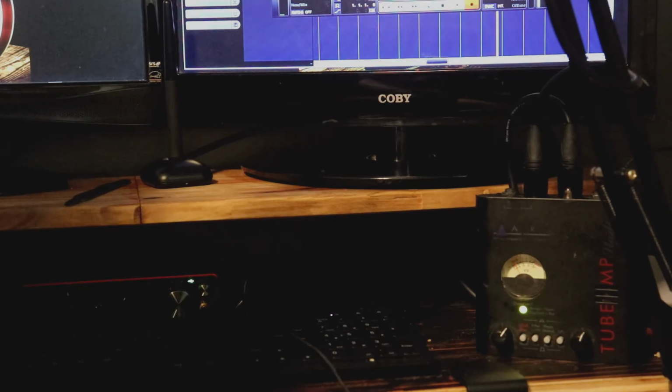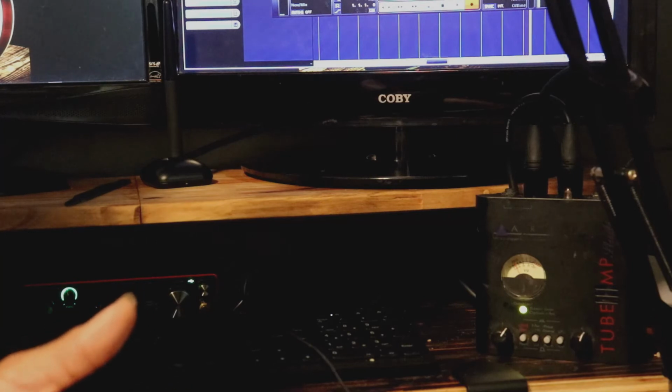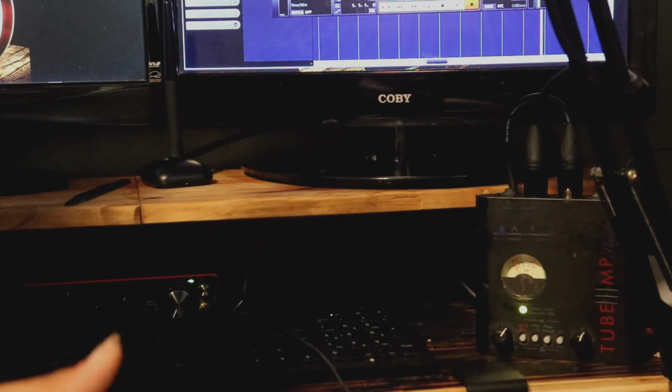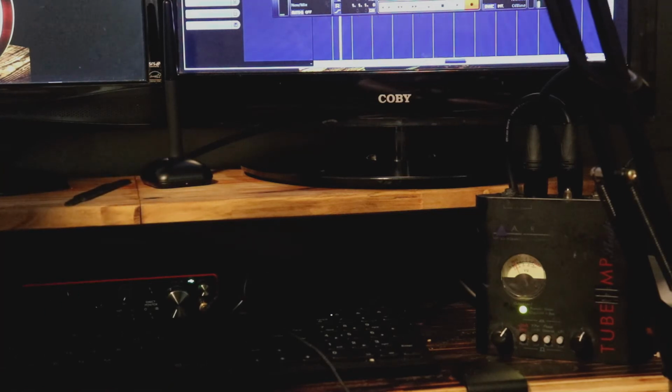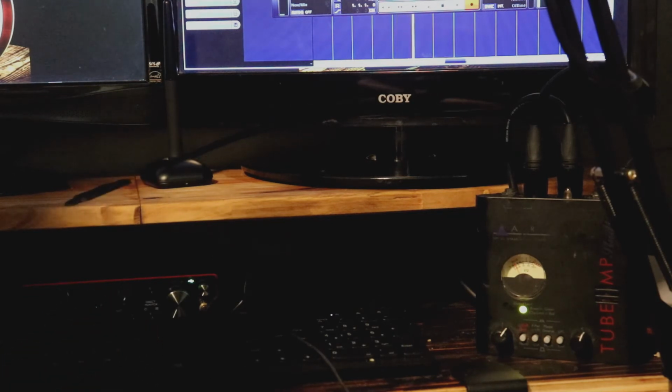And I'll talk about why in a few. Because op amps are basically low voltage semiconductors with very tiny resistors or transistors, the headroom you have available tends to be very limited, especially given the voltage that you might operate them at.